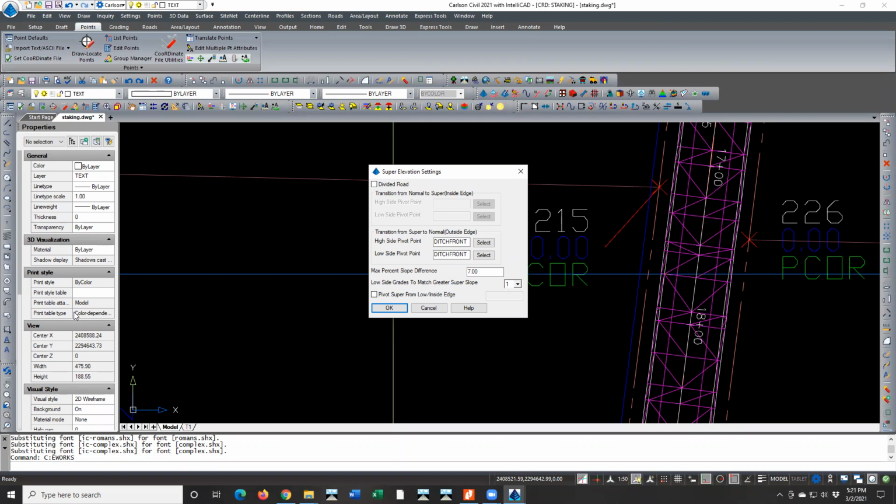So just at the beginning, from 1720, I'm at -2 on both sides, and then the outside goes to 0 at 17 plus 56, and then goes to +2 at 17 plus 92. So basically there's no crown. That's what they mean by remove crown. And then at that point, the left side and the right side need to transition.